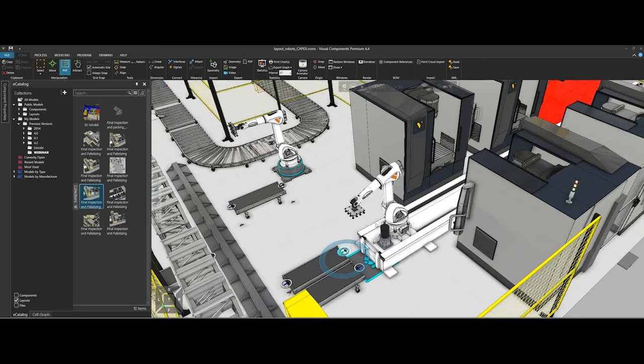Once you've won the job, once you've chosen the direction, once you're sure of the outcome, then, as Chris had mentioned before with their offline programming capability, you are 100% able to go in, teach that robot all of the points offline, and then through post processors take those points, export them into that robot's language, and upload it into the controller.